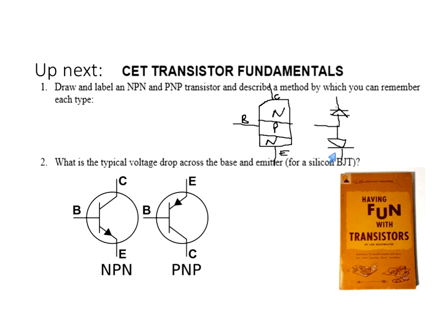And the collector is up there. Emitter, collector, and here's the base. Now, the way that we turn this transistor on is we apply a voltage on the base. And to turn a transistor on, you've got to forward bias this diode. And how do I forward bias this diode between here and here? I apply 0.7 on that diode's anode. That makes that diode turn on here and pulls this current right with it. So adding 0.7 onto the base is what turns the collector and the emitter on.